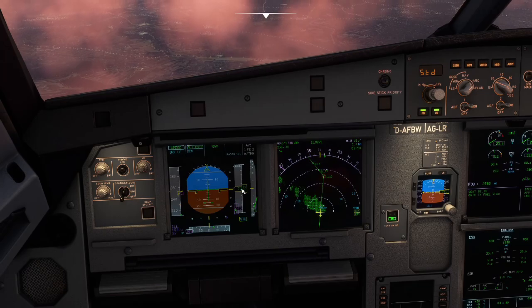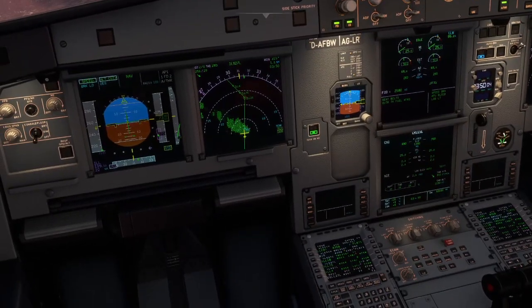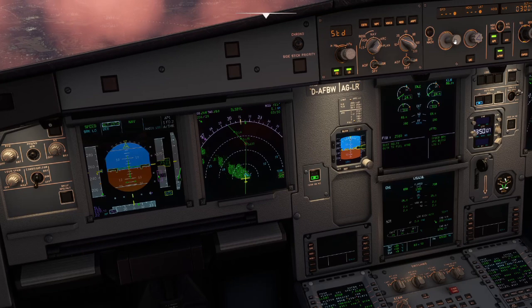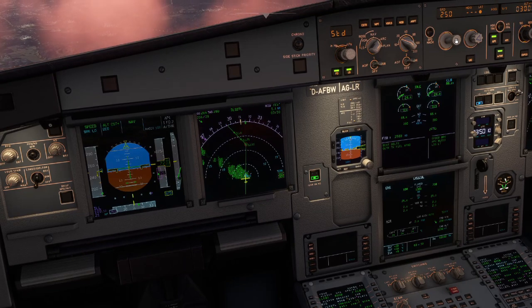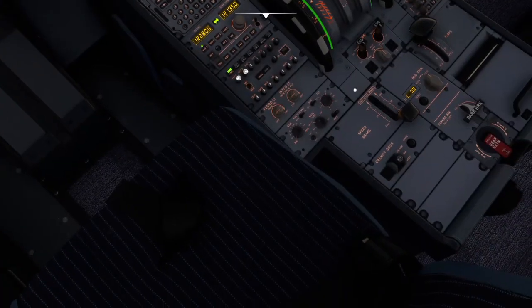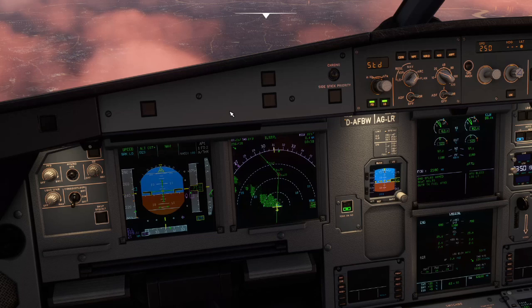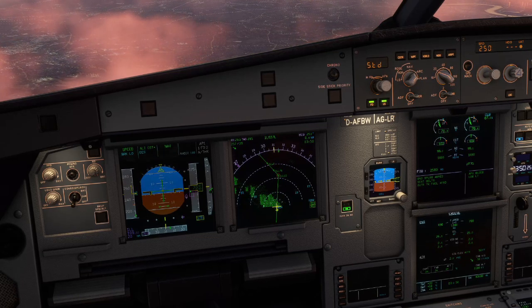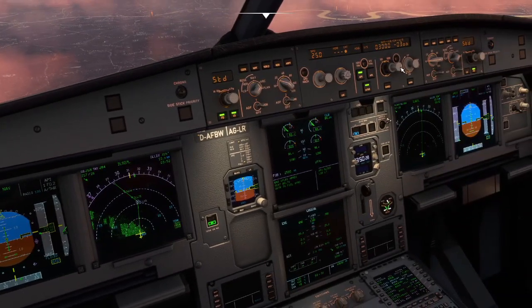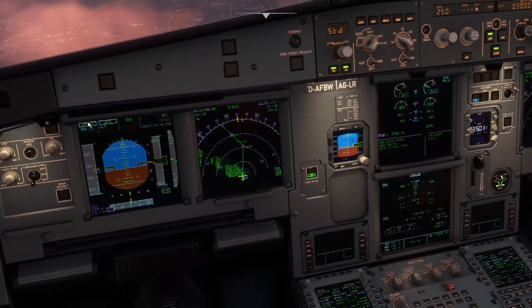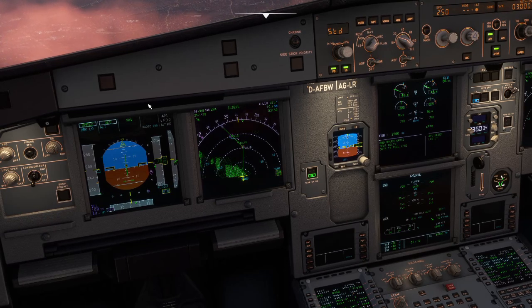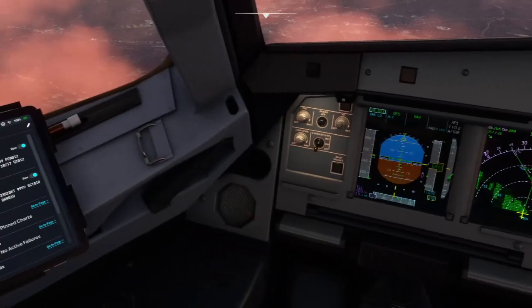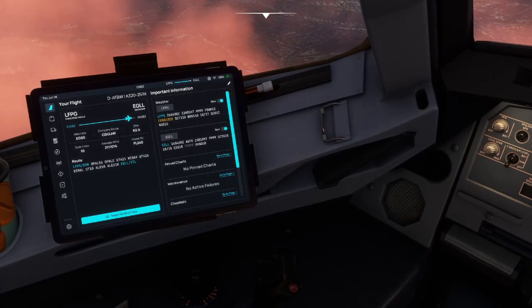There you go, it's just going back into an altitude constraint mode. My speed, for some wacky reason, has gone into approach mode, so I just did a speed intervention and it has done the altitude constraint. Alright. Yeah, that's a terrible example to show you. Tripped into vertical speed again there, so apparently it does not overly enjoy the constraints on this arrival.